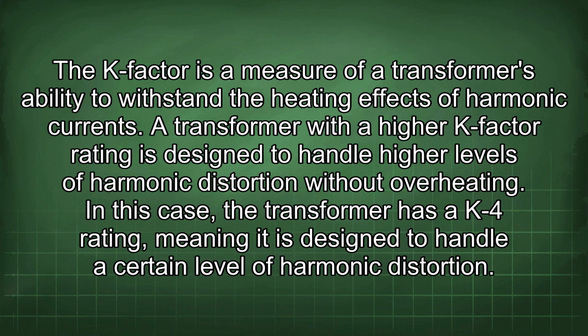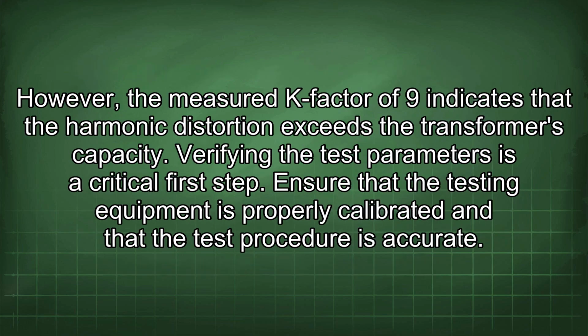A transformer with a higher K-factor rating is designed to handle high levels of harmonic distortion without overheating. In this case, the transformer has a K-4 rating, meaning it is designed to handle a certain level of harmonic distortion. However, the measured K-factor of 9 indicates that the harmonic distortion exceeds the transformer's capacity.